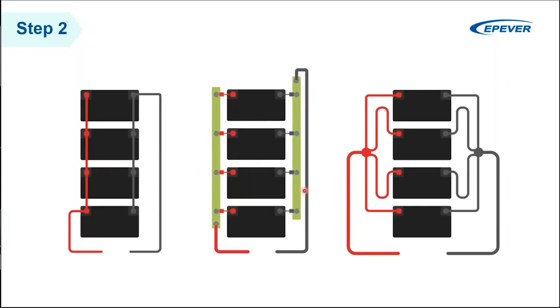These are the bus bars. You can use the bus bars for that, and you can use these kinds of cables. And why are these twisted? Because it has been taken into account that the length of this cable should be equal to the length of this cable, so that the resistance of all the cables is equal. So this was the point that I felt is worth mentioning here when we are designing the system.